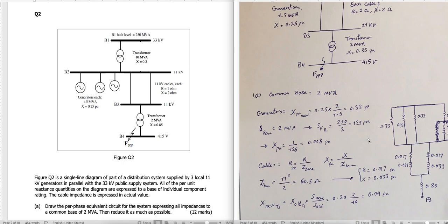But again, it's safer to put them there and just cross them and get it. Here, it's okay, it's correct, but I don't want you to make a mistake when you go to calculate base current, because for base current we don't have kilovolt squared, we have kilovolt and then power. So kilo is 1,000 times more, but mega is 1 million, so you should be careful.